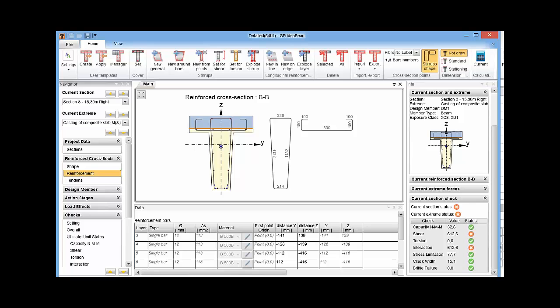Sometimes when we calculate the lever arm from response, then it is necessary. It is written in Eurocode, but I believe it is not. I would say in general cases it is not correct, and we should know how to avoid it.